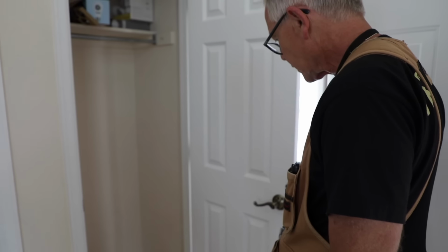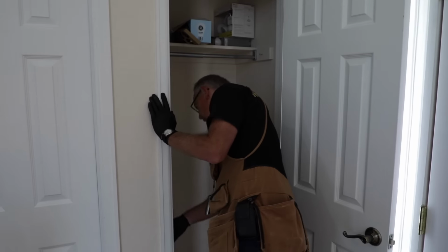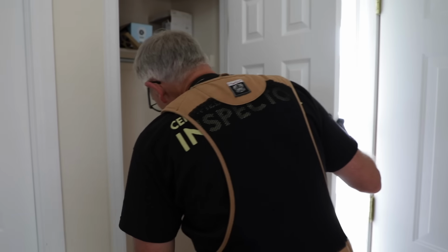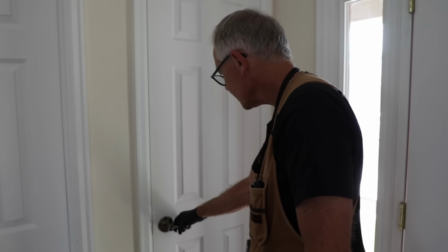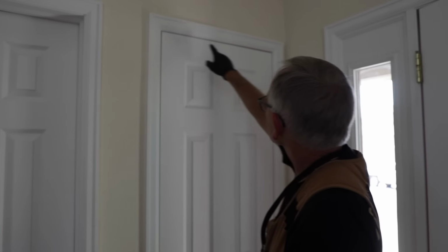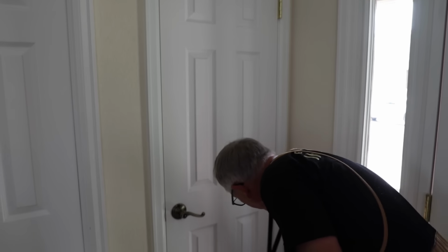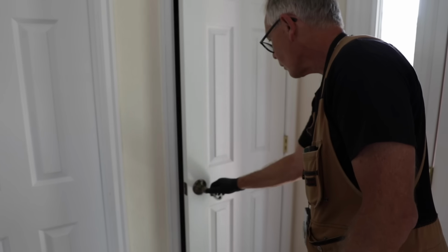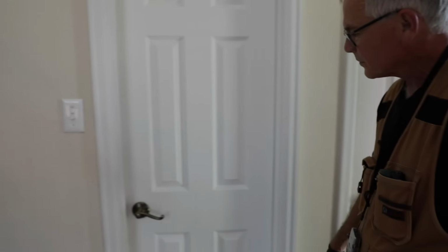Usually I want to just make sure I can open it all the way. Check the door frame, the jamb, make sure that I don't have any cracks, anything that might affect the operation. I'm going to go ahead and close and latch it. And then I'm going to check the gaps all the way around. Also look at the hinges too to make sure that you don't have any pins that are sticking up. And then just kind of rattle the door a little bit. I'll try it one more time. That door's good. Let's go ahead and move over to this one.